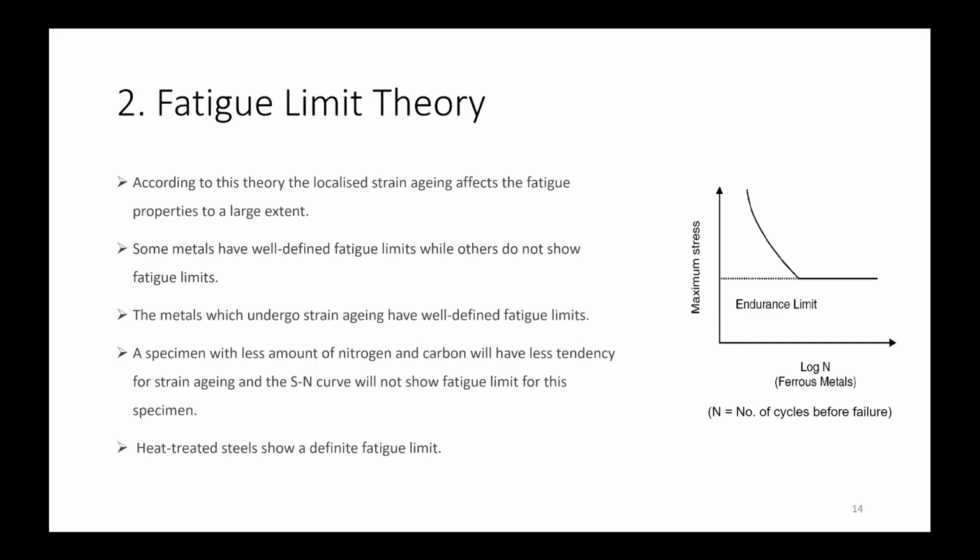And heat treated steels show a definite fatigue limit. Now this is your endurance limit at which your SN curve will become horizontal. If we apply a stress below this point, then your material won't fail even up to an infinite number of cycles.